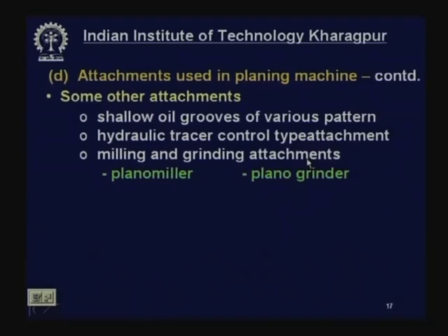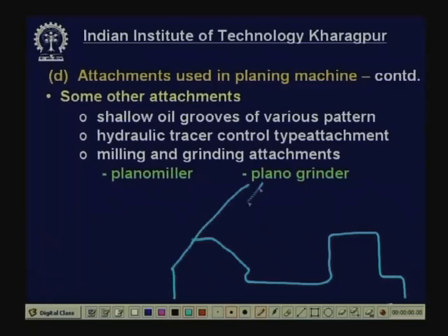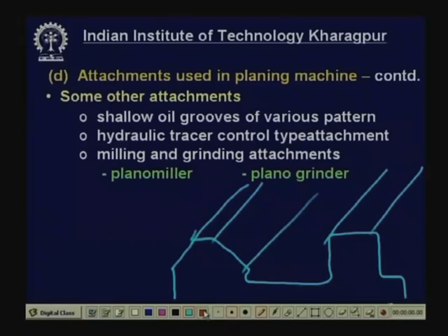What is it? Suppose this is the structure, the cross section of a large lathe bed or a machine bed. Now, this can be done in planing machines by single point tools, but single point tools are very low productive. So, then milling cutters can be used. Say one milling cutter will be used here, a face milling cutter. There will be another face milling cutter here,